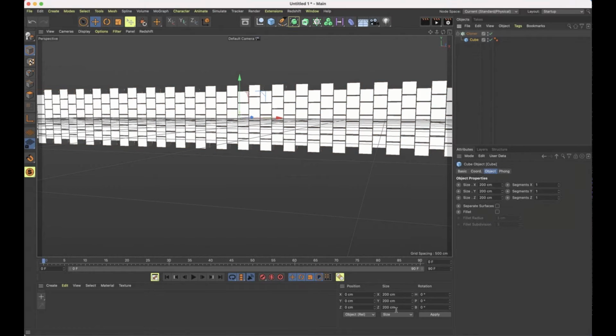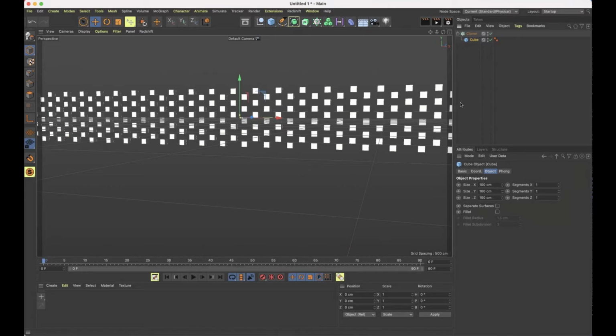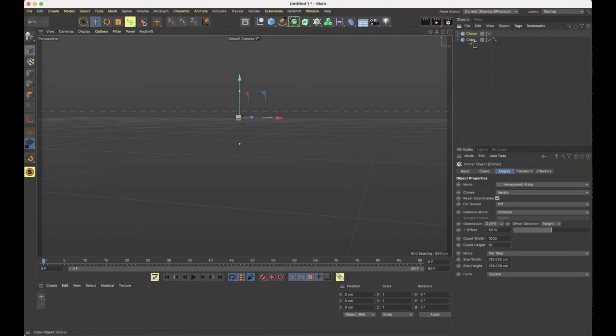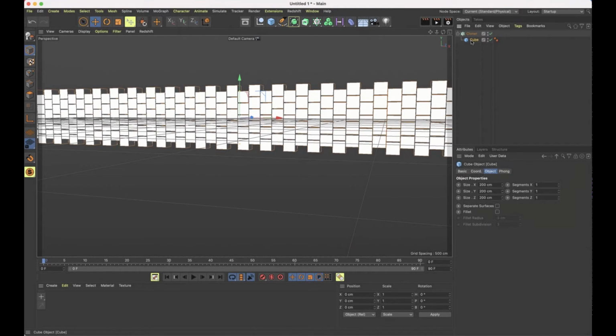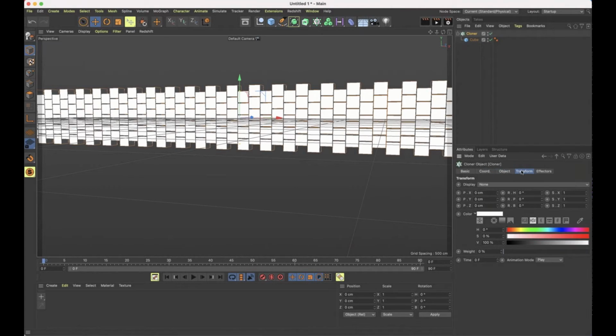So I'd recommend delete your cloner, get a fresh one so it's all default, and then drop it in, because it shouldn't resize. If you're using the scale, which is a slightly different thing because you're scaling the model, that should work. I don't know why you'd be having that issue. I've not seen that. Try clearing out your cloner and get a fresh one and see if you still have the same issue. And if you do, let us know and we'll try to figure it out.